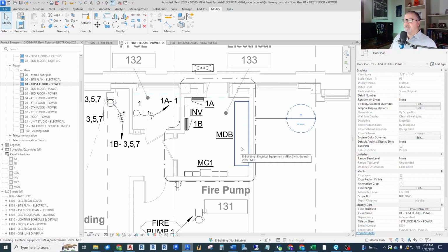Well, now that we can do this all in 3D and Revit, there's a lot of coordination that can happen between our conduits, ductwork, structure, plumbing, many other things. So we want to show large conduits, typically about 1.5 inches and larger, and their generic routing. Again, it'll change in the field when contractors get a hold of the field conditions out there.